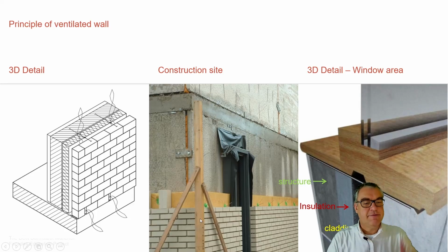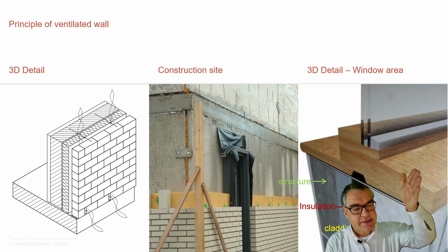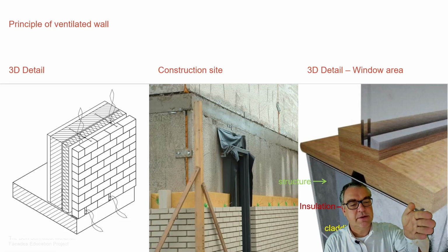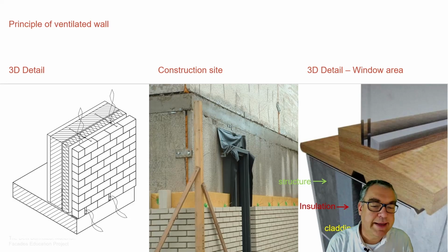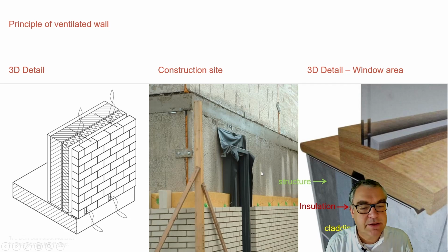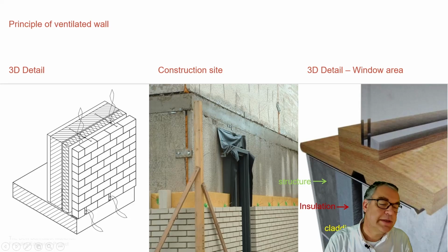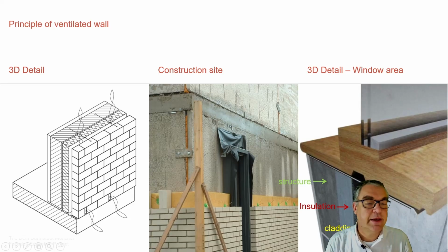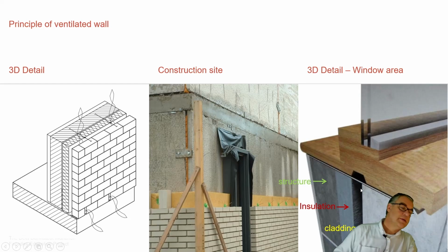We also have to identify that the outer masonry needs to be held in position because it is so slender that it will not be able to stay in position and not buckle when horizontally loaded. This means you have to have connectors between the outer masonry system and the inner main structure, which have to penetrate the insulation, obviously, and which have to fix the insulation, which we will see in one of the next slides. And yes, the window itself needs to be added.